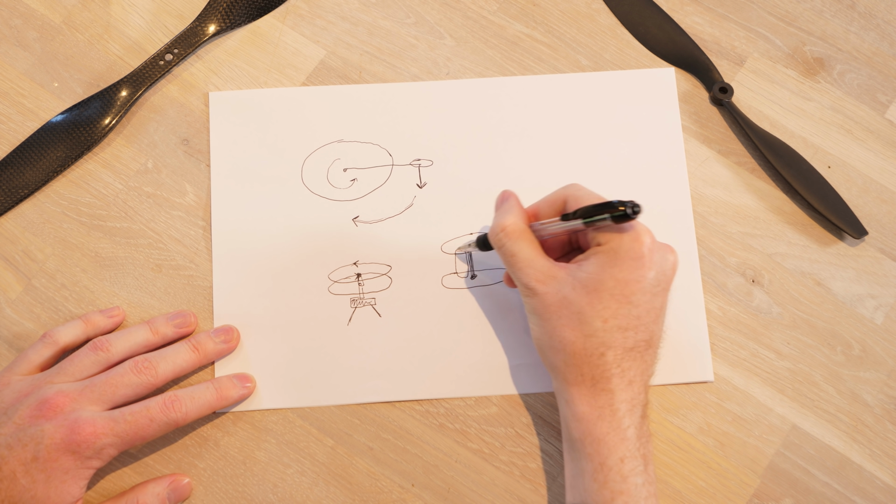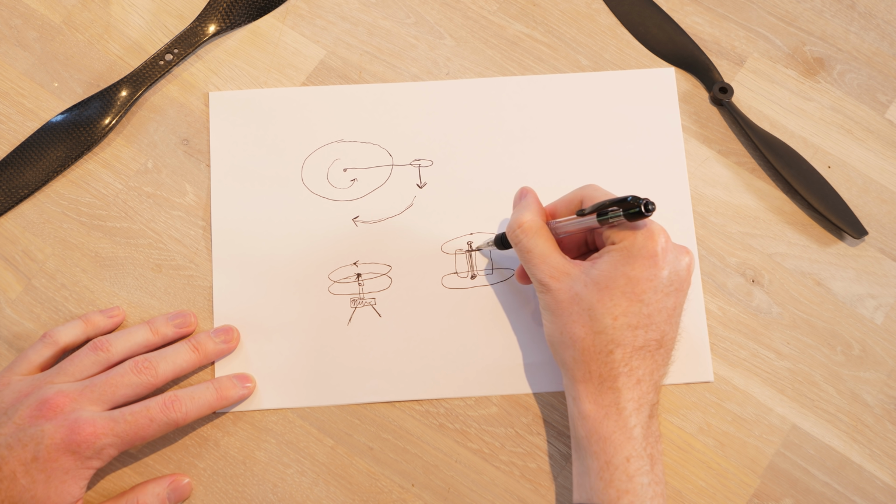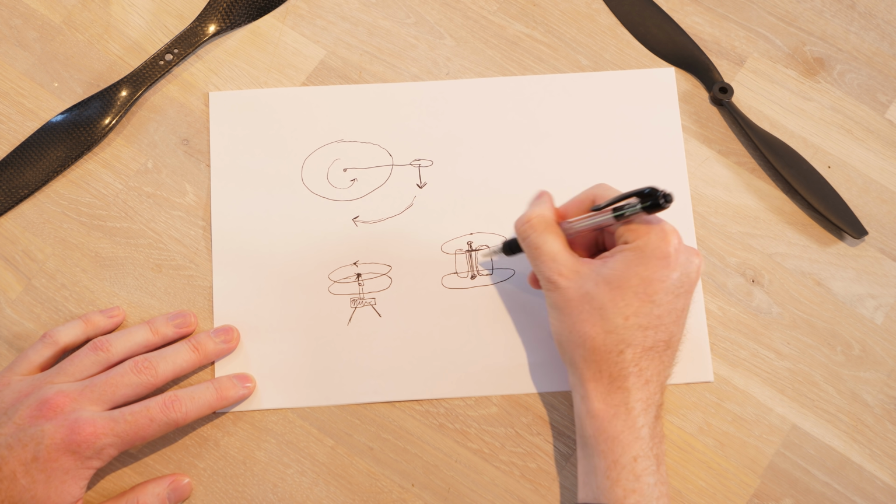Two turbines means added weight and also twice the air consumption. So we just add more compressed air bottles, right? Well, this starts to spiral into a vicious circle of needing more thrust, and then to produce more thrust we then need more compressed air storage, which then adds more weight, and then we need more thrust again to lift that extra weight, and so on.